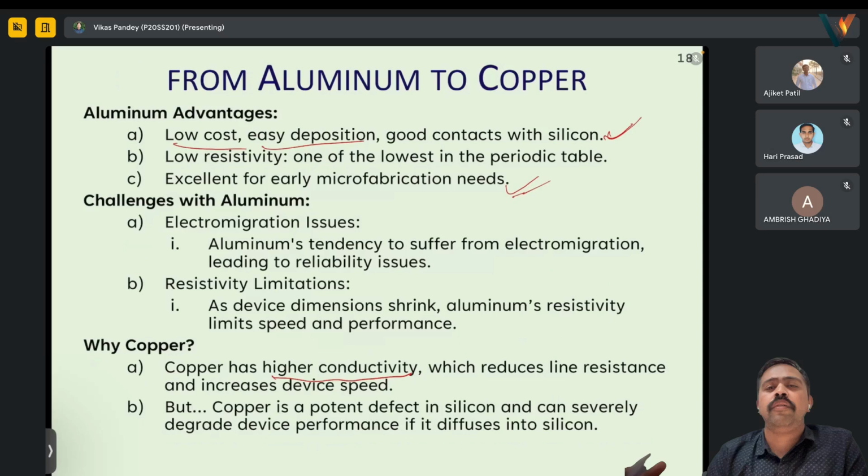There are processes with low energy like CVD and ALD, with high sticking probability, and the quality of CVD and ALD is much better. Sputtering or PVD methods have high sticking probability too. These are low-energy processes; they are not bombarded. Whereas if we are talking about sputtering, it has moderate energy and can lead to lower quality, and there can be damage also.